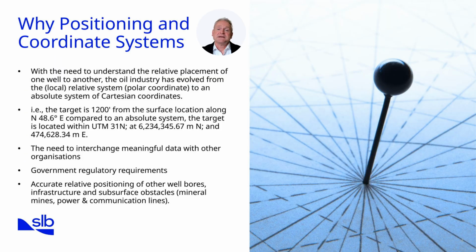In the oil and gas industry, accurate positioning is absolutely critical. Imagine needing to understand the relative placement of one well to another. Historically, the industry often relied on local relative coordinate systems, for example, saying a target is 1,200 feet away from the surface location along a certain bearing. While useful for local drilling, this approach becomes limiting when we need to integrate data across larger regions. That's why we've moved to absolute coordinate systems like Cartesian coordinates expressed in UTM.